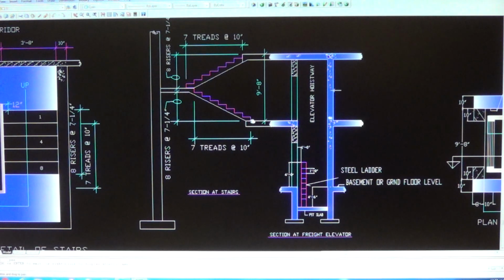If you want to know the total distance of a tread, you just add this up, so you know where exactly the tread is. And as I said, the minimum landing, this landing here, is 3 feet and 10 inches, and the other landing here with extension is 4 feet and 9 inches.